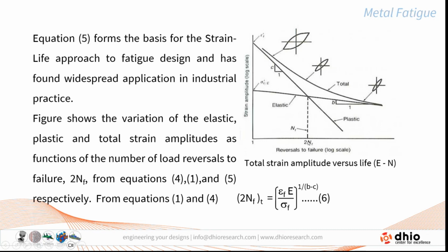Whereas anything with the number of cycles greater than NF, beyond this, it is the elastic portion of the strain which causes the fatigue failure. And the number of cycles to failure is related with the stress, strain and the Young's modulus, with the constants, which are the slopes of this curve.